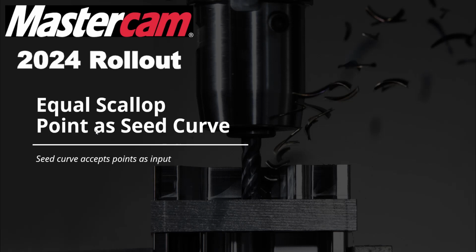Equal scallop was added a handful of years ago, effectively for me replacing the scallop toolpath. Now they left the scallop in there as well. They said that was a decision they made because there's such big changes to it. Instead of replacing it, all the legacy files would then need to be regenerated, and because all the changes could have got a little bit different varying results on legacy files. So they left the original scallop in, but they added the equal scallop.